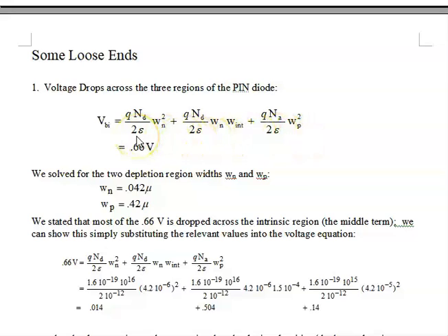This is from our previous session, and since the P was doped 10 to the 16th, and the N was doped 10 to the 15th, N to the 15th is 0.3 electron volts above intrinsic, and another order of magnitude is 60 millivolts higher, so 0.3 plus 0.36 is 0.66. That's the total drop across this three-layer structure, and we want to find out where the voltages are dropped, which gets more voltage and which gets less voltage.